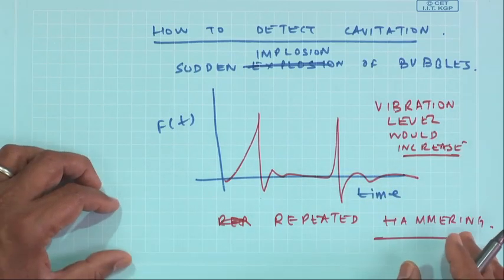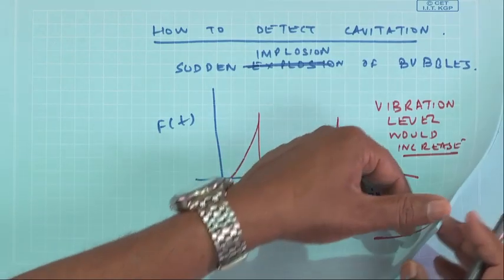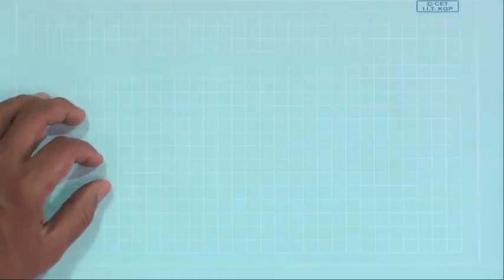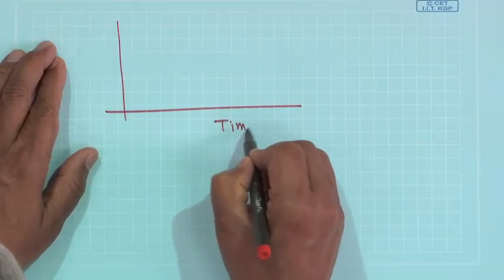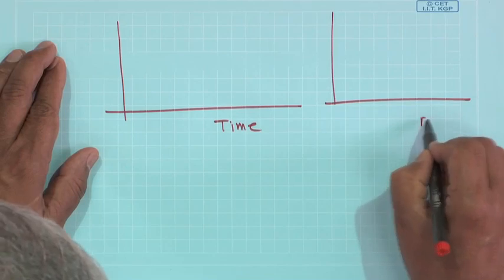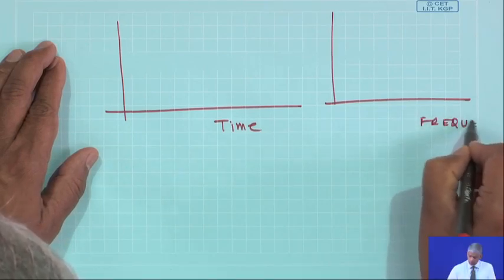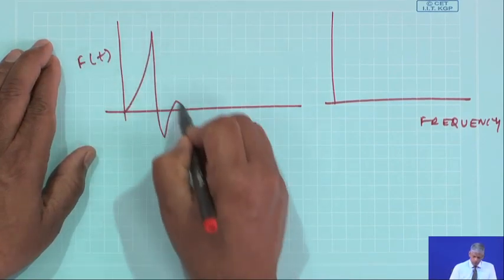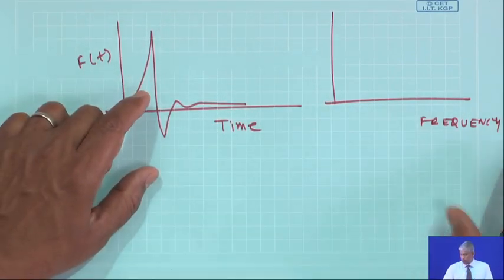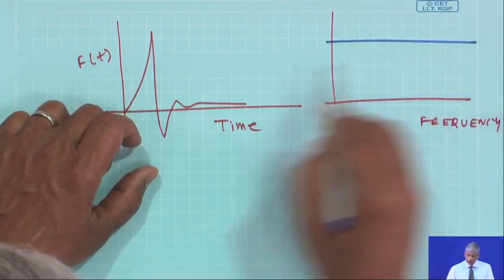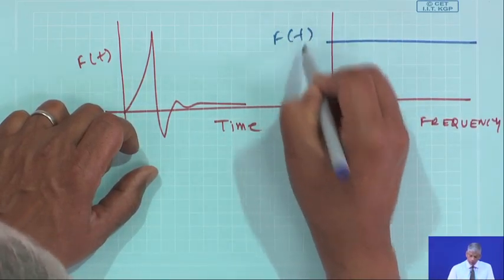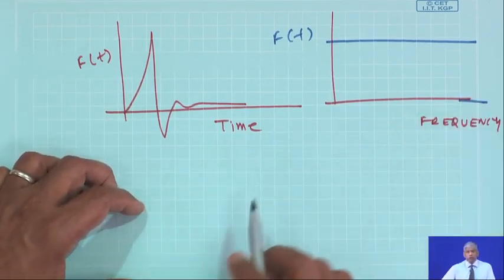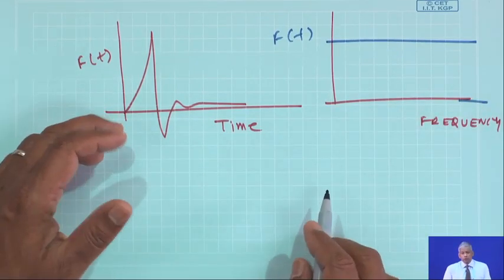But what can you say about the characteristic of the vibration level in terms of the frequency? And you all know from your experience with frequency and time signals, an impulse in the time domain because of one hammer will actually excite all frequencies. So, that means again very similar to the phenomena which I discussed during impacts in the races of the bearings.